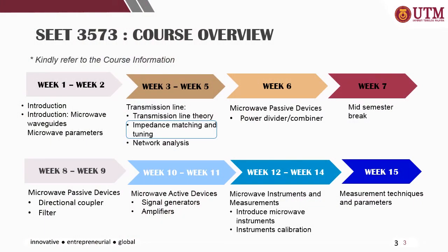Okay, basically we have discussed in detail how to solve circuit design or transmission line problems using the Smith chart. So today we are going to focus on the implementation, or the application, of microwave design using the Smith chart as well. We'll be using the concepts and basic knowledge you have learned from the Smith chart analysis to perform impedance matching and tuning.